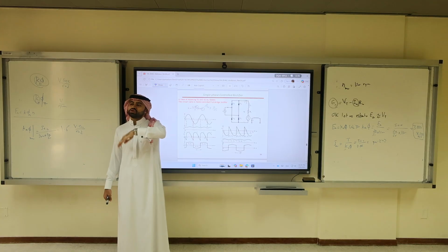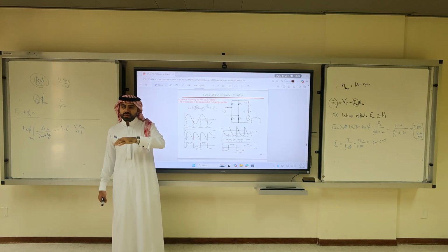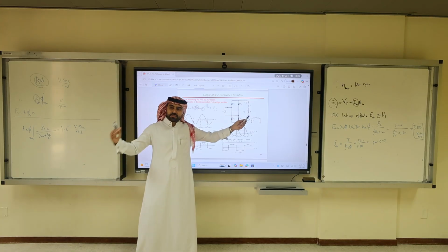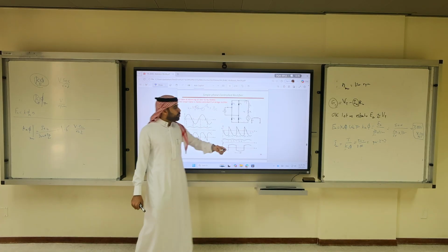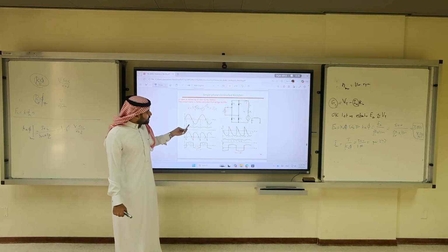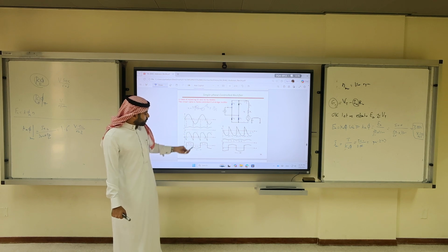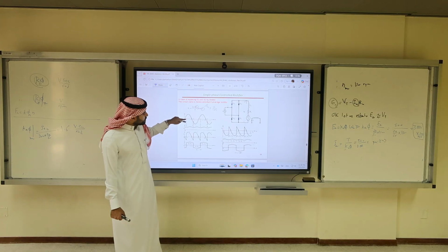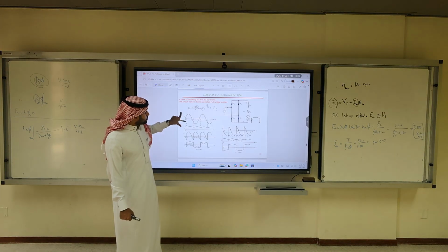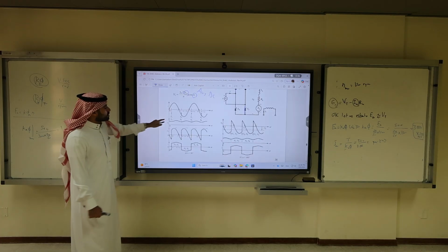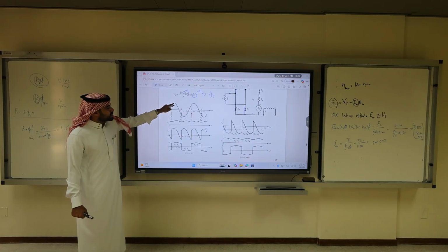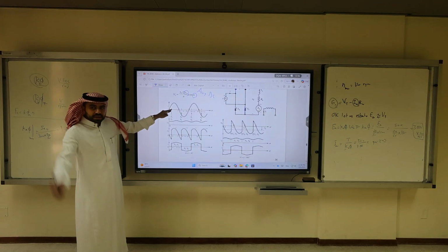The current cannot jump across the inductor, so this would limit the current burst to be smooth. Apply this at an alpha, for example, 45 degrees. So alpha 45 degrees is here. This is 45, this is 180. So at 45 degrees, send the pulse.